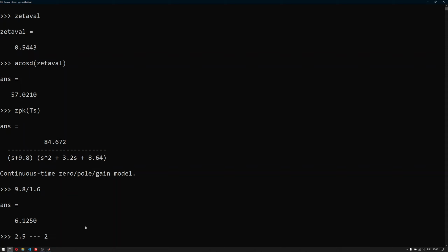close, because we have no other methods. We cannot come up with a settling time formula, or we don't have any settling time formula that gives us directly a relation between 3 poles and the settling time. The best we have is a second order polynomial, or 2 poles, or complex pole pair even, and a settling time, and we can assume that this should be far away and it will work. So that's what we got at this point.